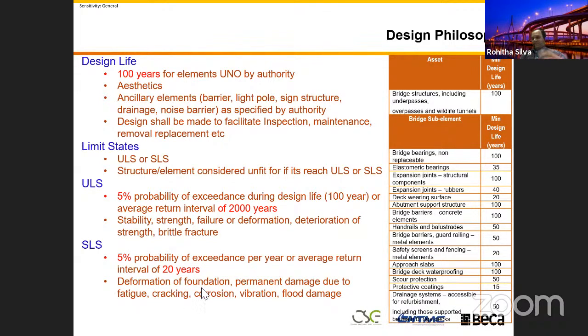We make sure the deformation of foundation, permanent damage due to fatigue, cracking, corrosion, vibration, flood damage, all those things we cover. For example, you can design a bridge with beams and everything, but when people are driving on there, people start complaining the bridge is vibrating. It's very difficult for us to stay in traffic. So there are a lot of situations.